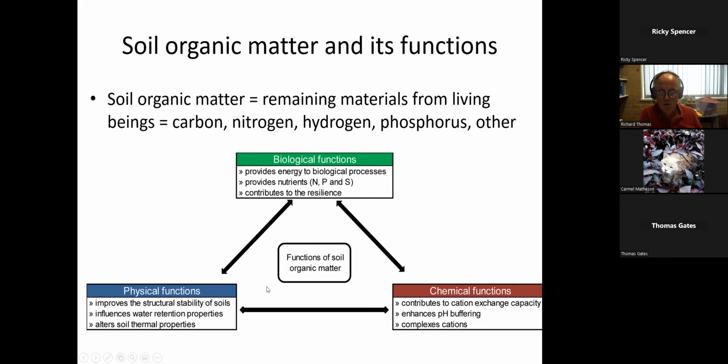So inside the soil, we've got physical functions which come from the organic materials and the inorganic material from which it's derived. We've got chemical functions, in that the structure of the soil can change its holding capacity. Water holding capacity influences how the pH is controlled, whether it fluctuates a lot, because metal ions can be held and released and buffer the pH to a certain level. And then the biological functions, how healthy the soil is, depend on the carbon content.